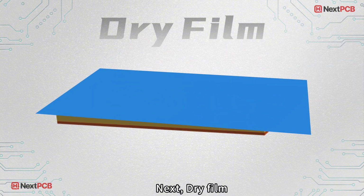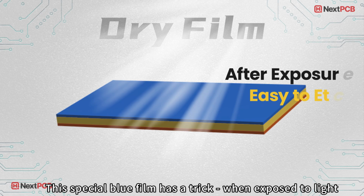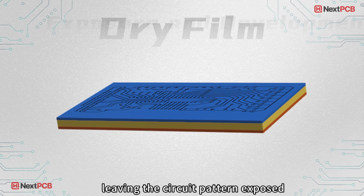Next, dry film. We cover the board with a blue photosensitive dry film. This special blue film has a trick. When exposed to light, it dissolves easily in developer solution, leaving the circuit pattern exposed.